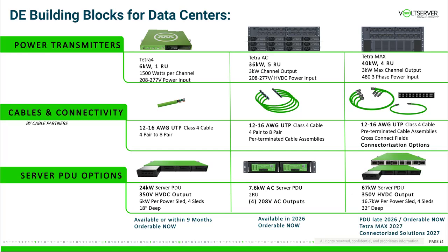So what's really cool about fault managed power is that doing that power adaptation at the end allows for flexibility at the server cabinet level, so that you could use a high voltage DC, which is the most efficient, lowest cost format, or you could use a low voltage DC distribution at the server cabinet, or you could use an AC distribution at the server cabinet as well.